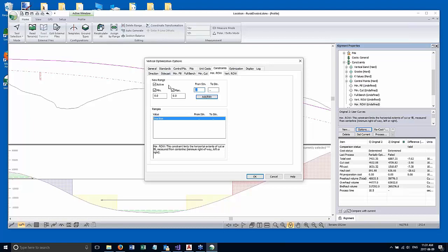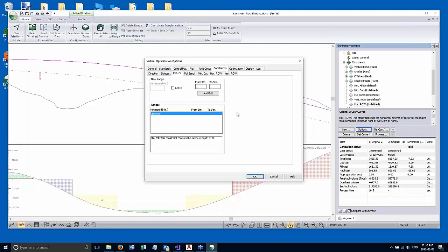Some other constraints that are often used in an area that's a poor material or something, you can have a minimum fill height above it. Classic for that is sort of northern muskeg situation where you need material on top of the road, so you force a minimum fill. Steep ground, you need a full bench cut, and so on. So all these constraints do is they clamp the alignment down and prevent it from moving in places that might be cheaper for various reasons.